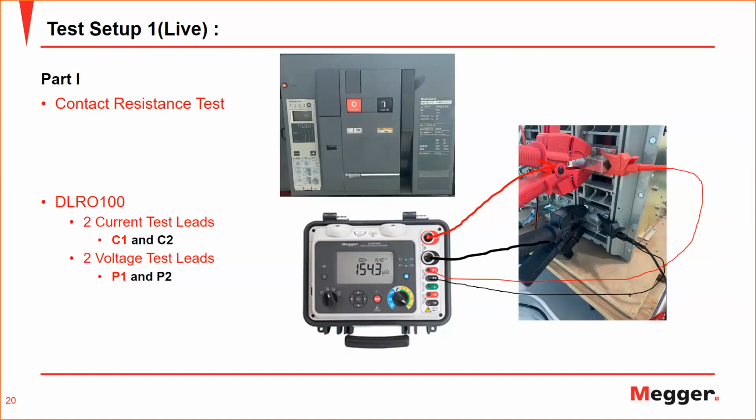And as I mentioned earlier, we will have a 2- or 4-wire measurement. Two will be the current leads, where they will inject the current. I will inject 100 amps. And two cables or leads will be measuring the voltage to get the resistance value.